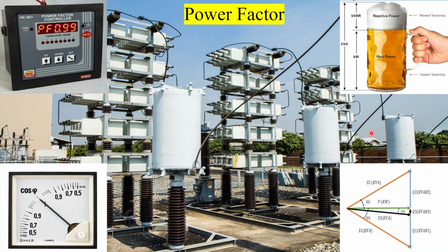Using a synchronous condenser: these are specialized synchronous motors that can adjust the power factor by varying their excitation. Installing power factor correction equipment: devices that automatically adjust the power factor to an optimal level.